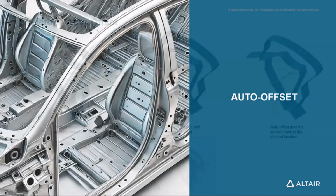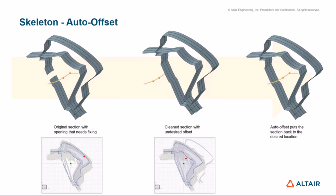So during the skeleton workflow, many steps that Stuart was showing before have been performed automatically. The logic is, first of all, we cut the donor elements with the slice. We automatically create the sections and the beams with the 1D element discretization, and we assign the section to the beams.